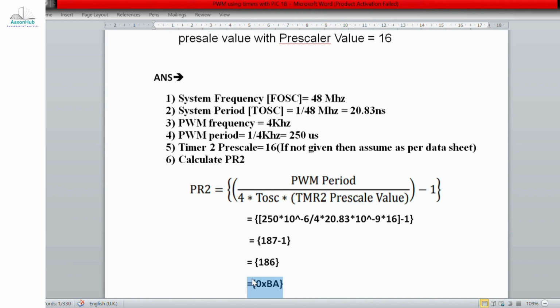In pulse width modulation, as a CCP module is used, a 10-bit resolution output will be there. As per that, the CCP2 is multiplexed with the port B and port C data latch. So the appropriate TRIS bit must be cleared to make the CCP2 pin an output pin.